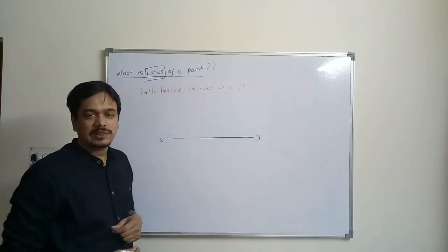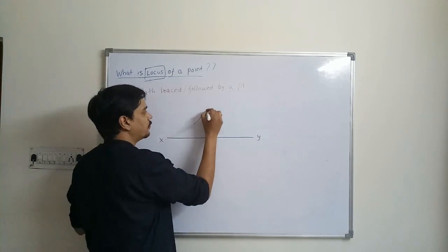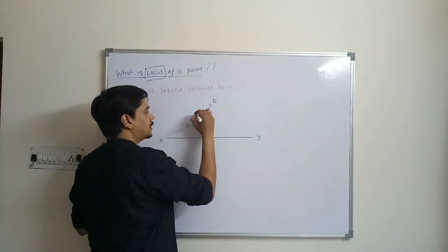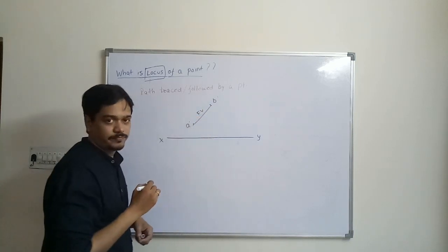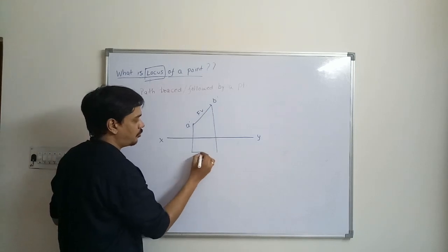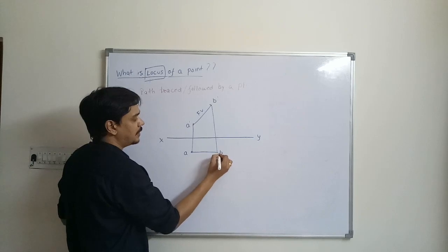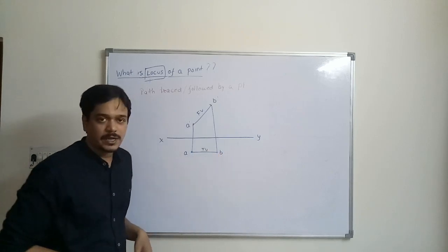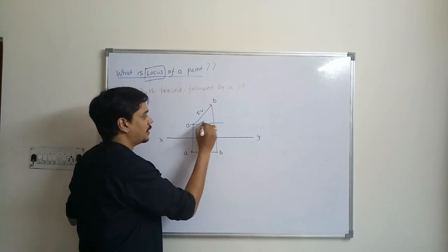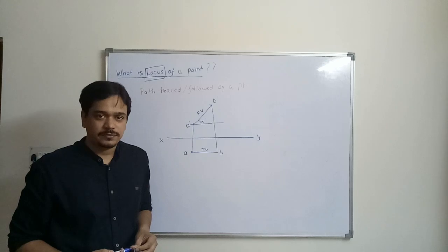that your line is only inclined to one plane, that is the horizontal plane, so this is A dash, B dash representing the front view, and you are drawing its corresponding top view. So it is a line parallel to VP and inclined to HP. So this is nothing but alpha. Now what is the locus?